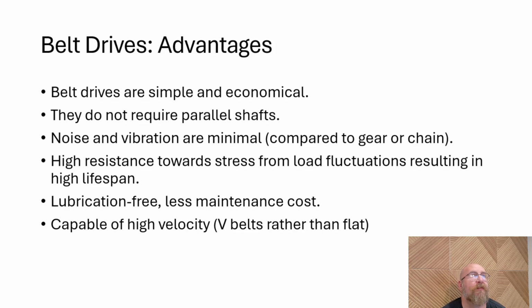So the advantages. Belt drives are simple and economical. They do not require parallel shafts. The noise and vibrations are minimal compared to a chain or a gear, because it's a flexible material that's transmitting that.